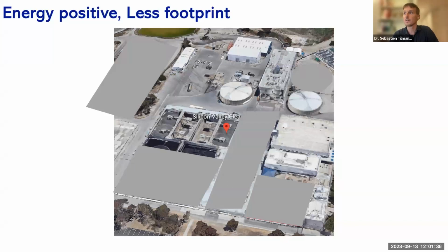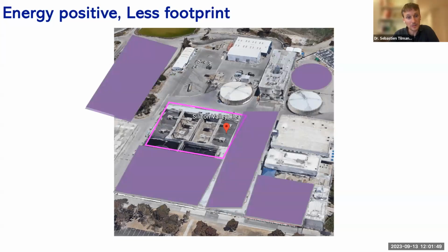So all of this footprint, what could you do with it? Well, you fit your SAF-MBR treatment process to meet secondary effluent standards within this pink square here, and this remaining square footage that you've saved is now the space that you can use to pursue water reuse. One of the big challenges of a lot of wastewater treatment plants is they're constrained in footprint. And if you want to start adding additional treatment processes to achieve water qualities for water reuse, the question is, where do you put them?